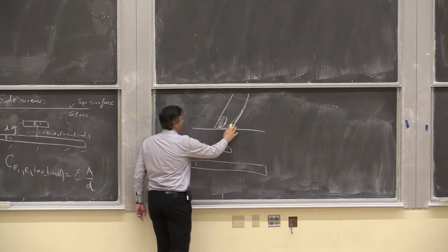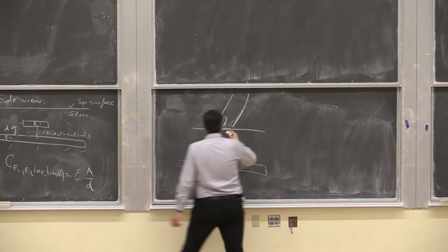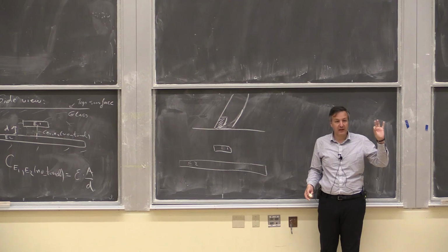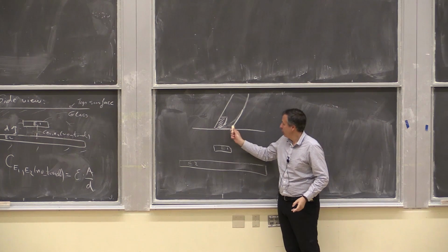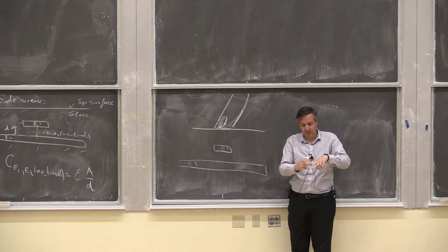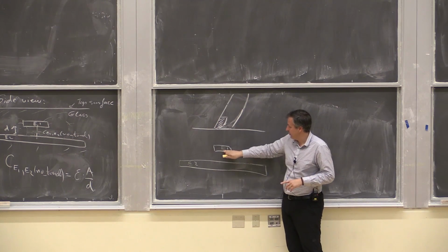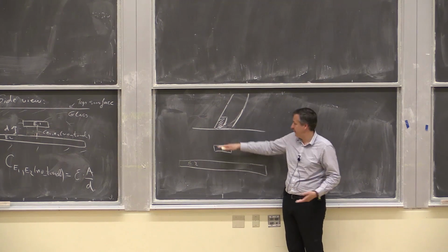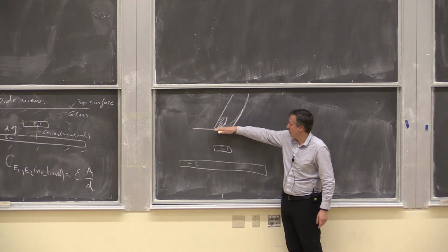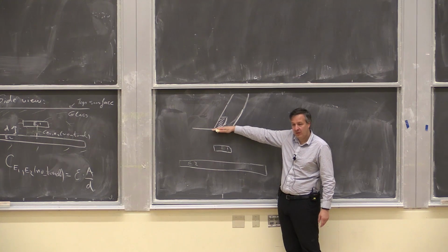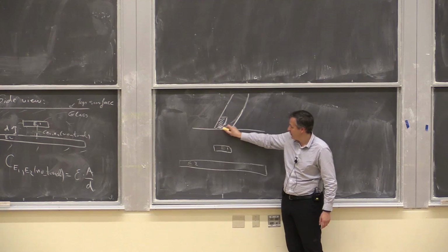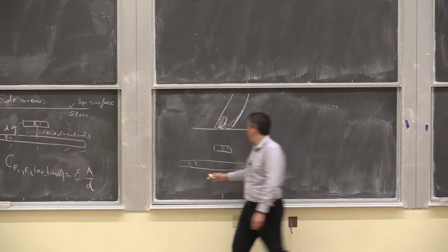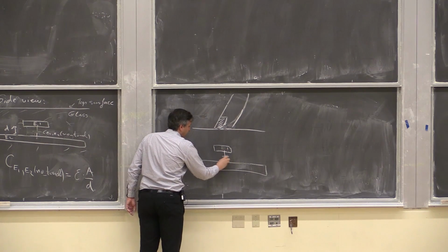Okay, it's my artistic rendering of a finger. So now when you put a finger on, we said that the skin is conductive, right? So basically, the whole everything on the finger is conductive. But again, just like with the other electrodes, we're mostly going to look at the bottom plate. So it's essentially how this plate, if there was charge here, how the field of that charge terminates on this wire and that wire. Right. So effectively, what you have here is this capacitance that we already had.